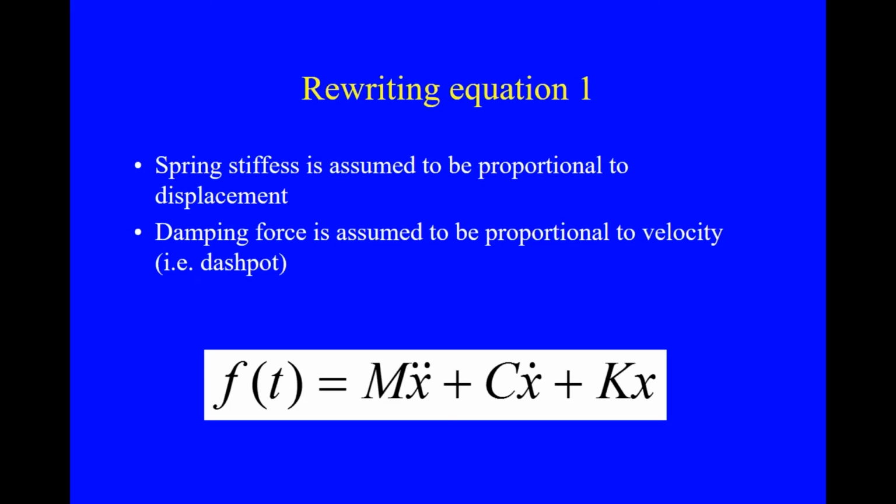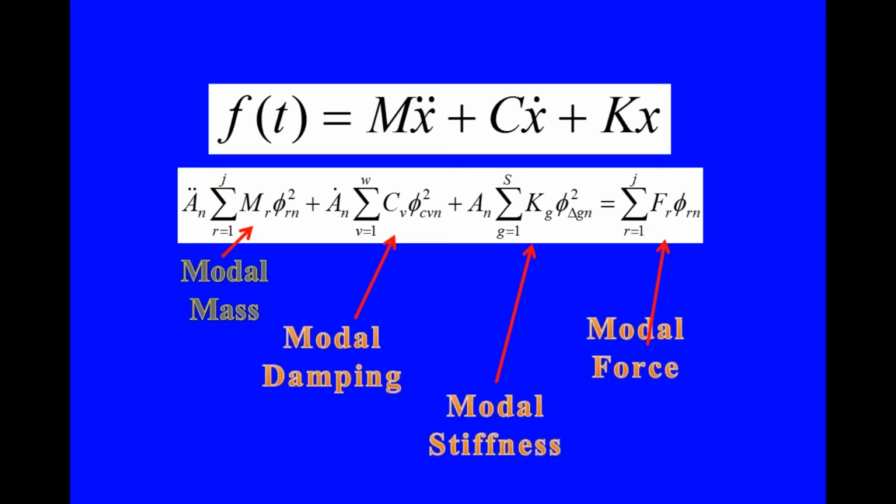And under those circumstances, what you have is really micro behavior. You have molecular behavior. How do I know this? Because we've taken samples out of a building in Hong Kong that was hit by a typhoon within a week of being constructed. And we looked at samples where the stresses were smaller and where they were larger, and we found chemical differences to the cement paste taken from the same site, same batches, in which the energy had appeared as changes to the chemistry of the cement. That was a surprise too.